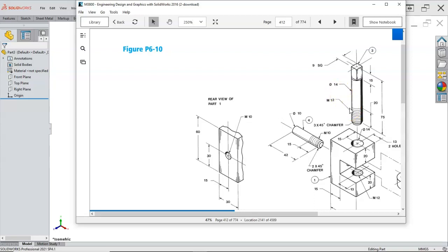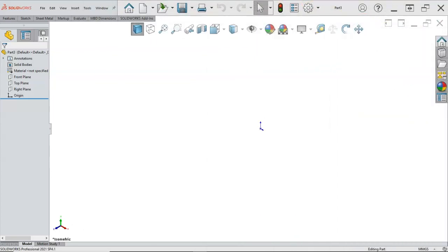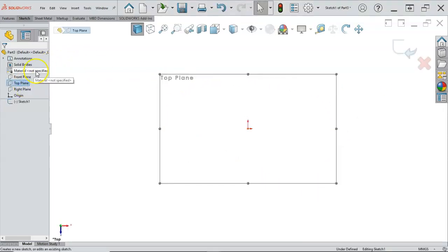So that might be better to do the revolve after all. So the major diameter of the 12 millimeter would go to and then step up to the 14 millimeter diameter. All right, so let's do that. If you see it as a revolve and you want to do it as a revolve, go ahead. Since I said I was going to go with the circles.